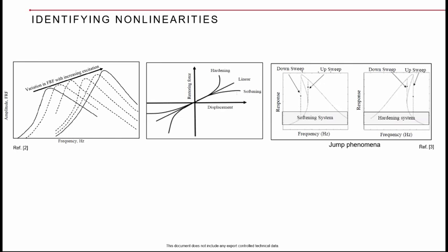So how do we establish that? You have to test sufficiently with increasing levels of excitation, from 1G till 10G, for example. At various steps you sweep your system, then you plot them, and if the frequencies are quite different, then it is a nonlinear behavior. This behavior can now be characterized by curve fitting, the natural frequency as a function of the stiffness. You can bring that stiffness in as either a cubic nonlinearity or a polynomial nonlinearity in your equation of motion, and then you can try to solve that equation of motion to get the overall response.